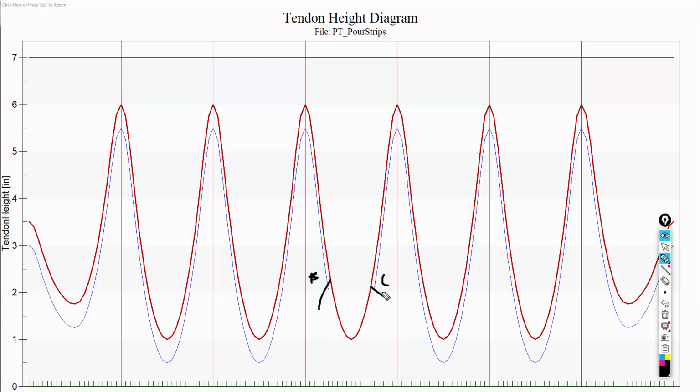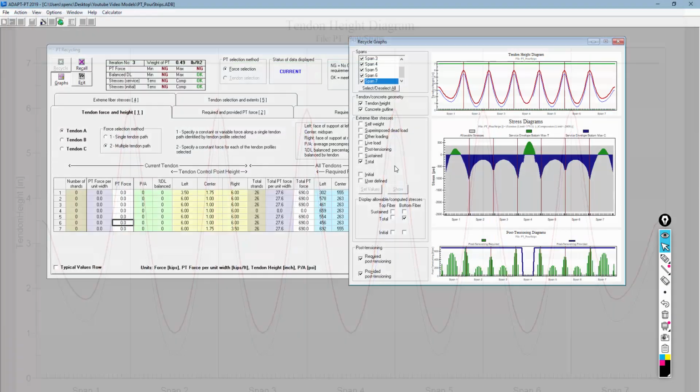no post-tensioning. And if we prepare a stress calculation, we know that if there's no counteractive equivalent loading from the post-tensioning, we're going to get significantly higher stress than if there was counteractive loads from the PT. We're not doing any load balancing essentially. So at that location, you can see we have high stress, and that's okay. This is not being designed as post-tension, so this exceeds the allowable.